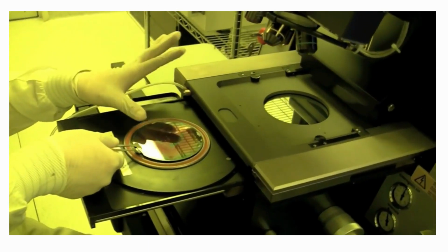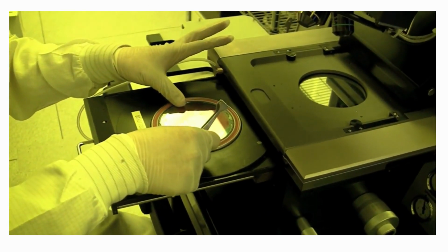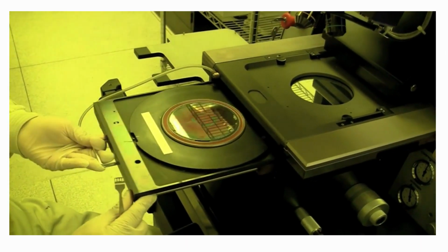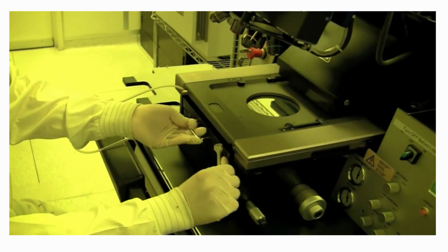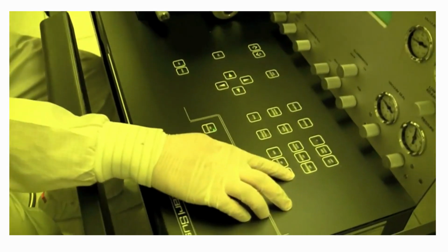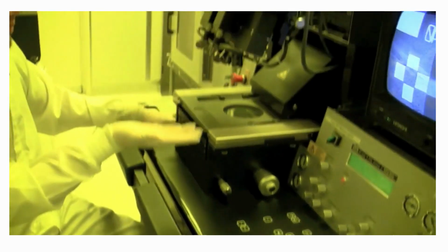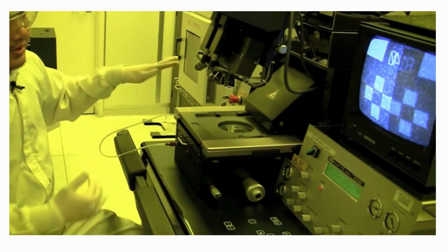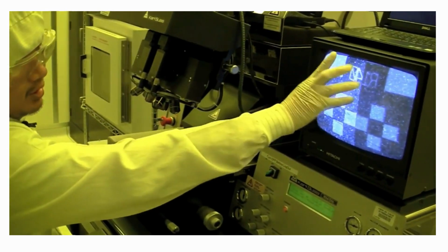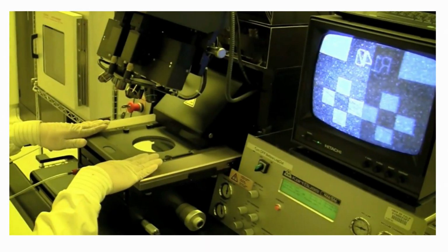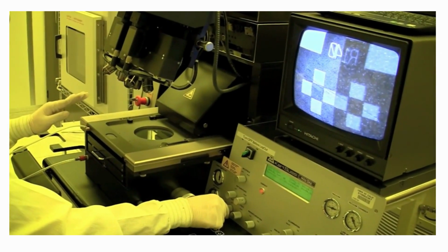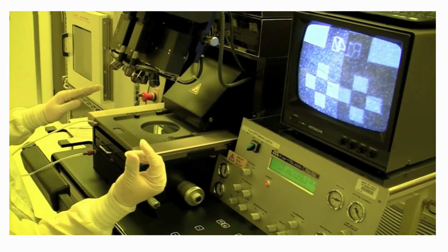And we will just load our wafer on. And when it's in, you press enter, and it'll bring it up. So now you can see you're in contact. This is the image overlay from the mask. And these features right here, see, they're the bottom substrate of your wafer.